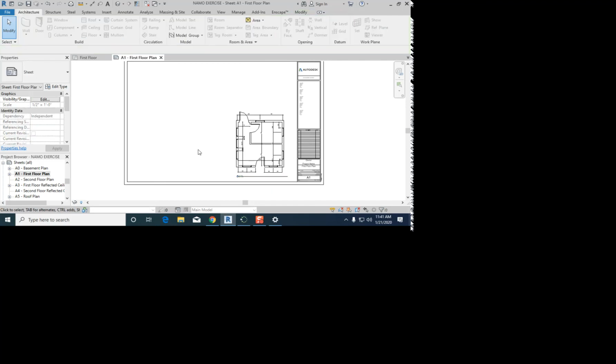I will be pretty OCD about how you guys turn stuff in. It's just because these drawings represent you, and I want them to look professional, right off the bat. In these classes, from the first assignments, the first time I probably won't mark you down, I will just make comments. But I realize that most people don't read the comments until they get marked down. So just watch out for that. I either want things to be centered or in the lower right. I want the view title corresponding with the view. I don't want crop view ons.